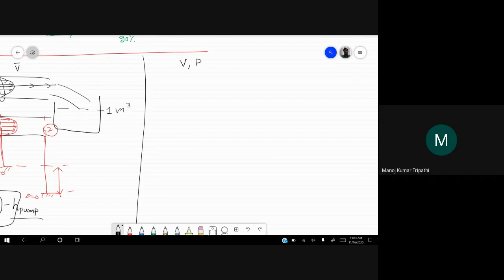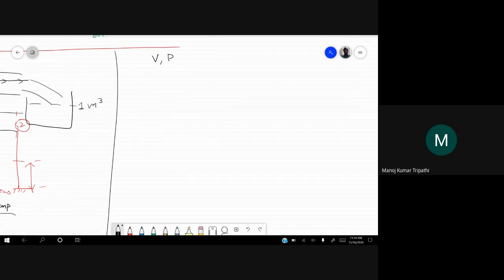Pressure sensors are there. So they can be in the form of piezoelectric sensors. So the devices which generate some electrical pulse on the application of some pressure on them. So those are there. Those are there for solids as well. Okay. If a solid applies pressure on a piezoelectric sensor, then it will give some electrical pulse, and you can measure the pressure. Same principle can be applied for fluid also. So that way you can measure pressures.